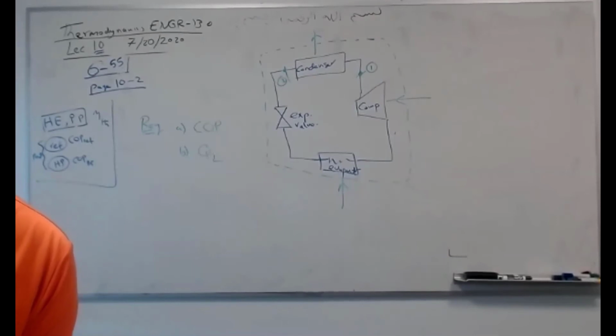Refrigerant fluid 134A enters the condenser of a residential heat pump HP at 800 kilopascal. So this is the entrance. I actually plot for you the condenser, and it enters with 800 kilopascal and 35 Celsius at a rate of, this is a mass flow rate, and leaves as saturated liquid. It means X equals 0.